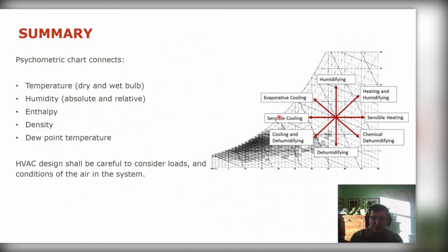And we looked at the dew point and the importance of it, both for condensation that we want, for example when we're dehumidifying the air, but also condensation we maybe don't want, like in the corners of rooms. And we looked at a couple of different processes and explained how you can map them easily with your inside air conditions, outside air conditions, mixed conditions, cooling, heating, dehumidification. You can work out your cycles, graphically represent them, and better understand the energy balances inside your HVAC systems. So I hope this brief overview was useful and you have a clearer view of how psychrometric charts and calculations can help you in your design. That's all I wanted to cover today, and I think now we can go over to the questions.